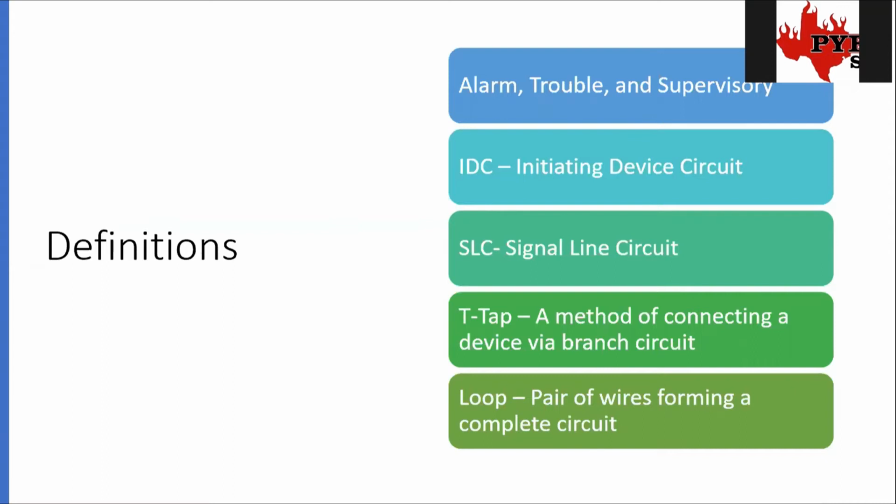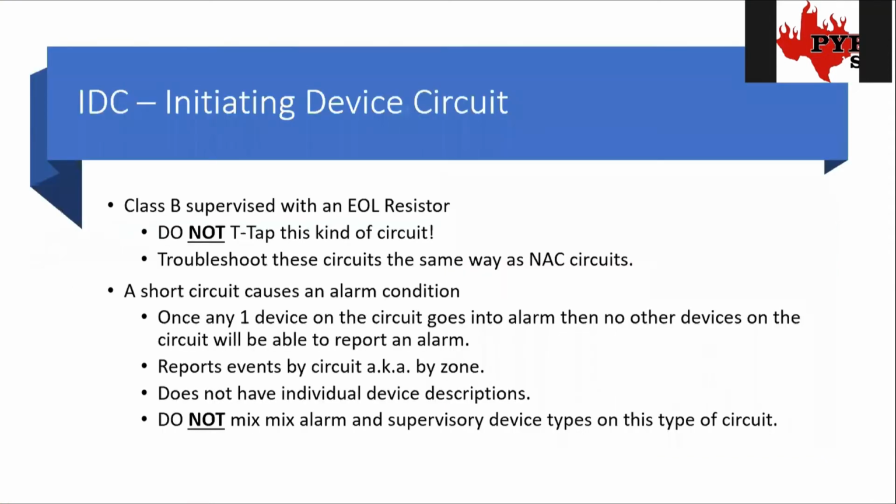So now we'll dive into IDC circuits. These are the initiating device circuits. Just like our NAC circuits and our speaker circuits that we've been talking about, these have an end-of-line resistor and they're supervised that same way.